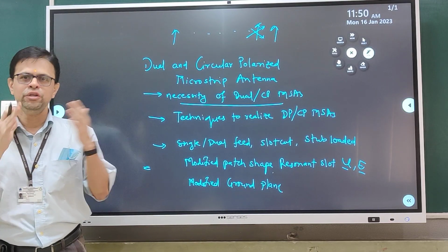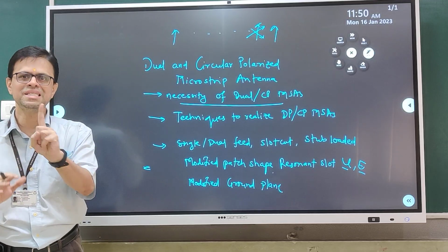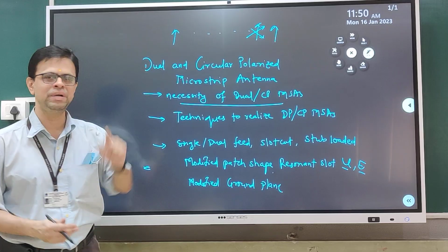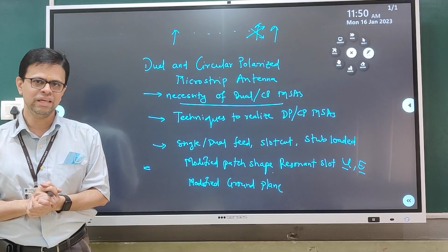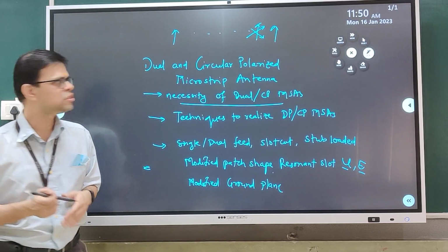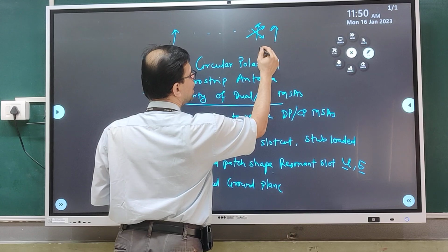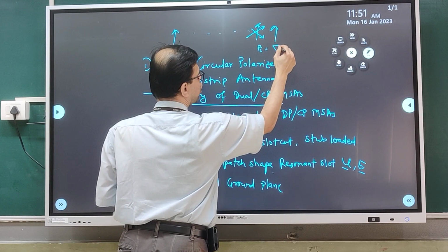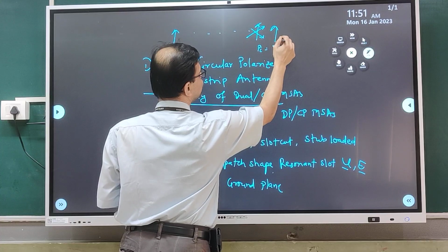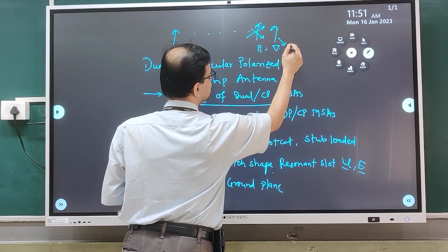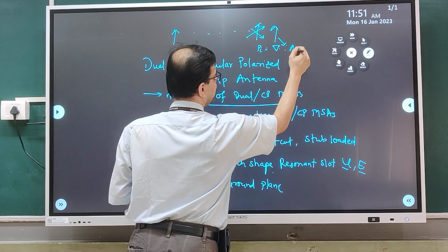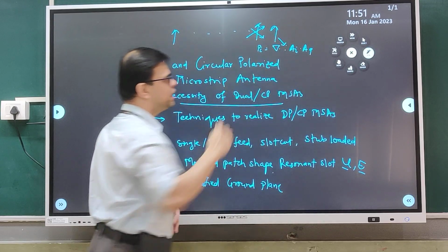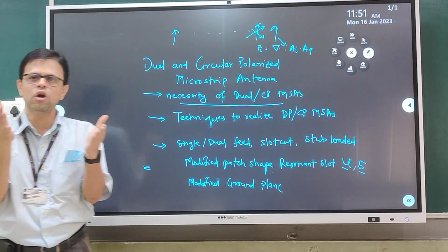Now if your receiver is only sensitive to vertical polarized antenna, because my transmitter is vertical polarized, then you will have a signal loss, because we know the output received signal is proportional to the dot product of these two vectors. So it is going to be the incident wave Ai into the polarization of the antenna. So it is basically a dot product.